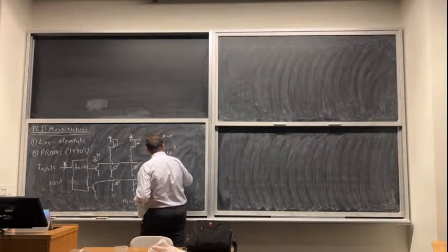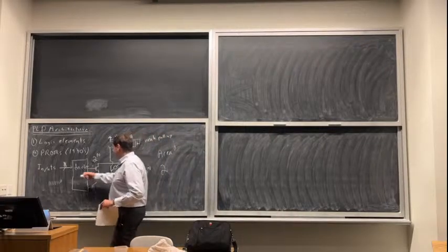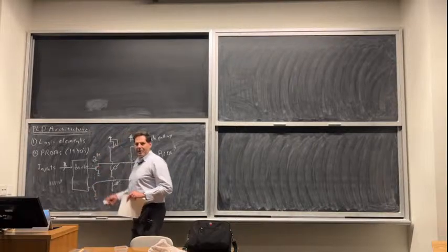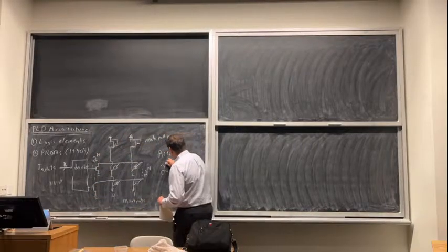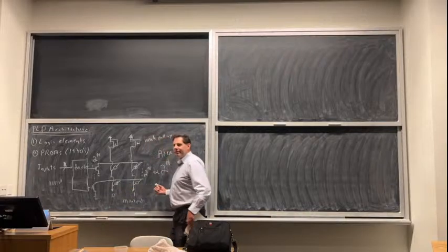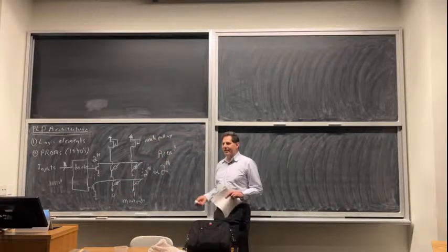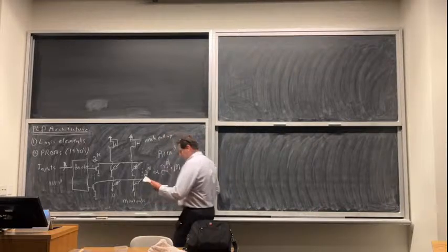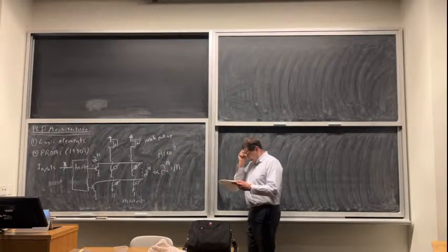Exponential, yeah. With inputs, basically the size of this decoder, the number of its outputs, is going to grow exponentially. So with number of inputs, it's going to grow with 2 to the n. What about with number of outputs? What do you think? It's linear, so number of outputs is not as bad. But this is pretty big.